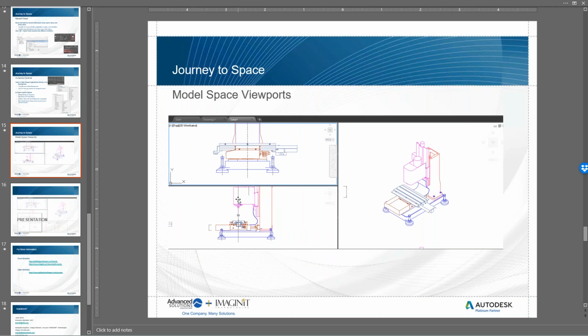In that case, you can have a view for a single three-dimensional object in multiple viewports showing in different orientations. Each orientation will be modified based on the model space, so a single model can identify multiple viewports with different directions of the same content, and you don't even have to modify the viewports when printing. The sheet layout information will do that for you.